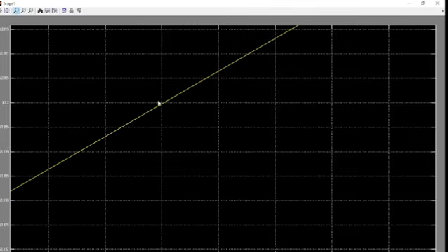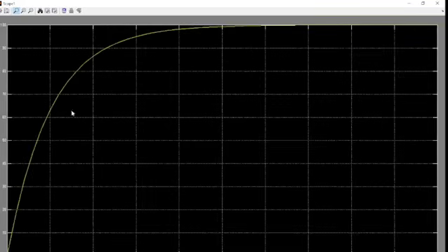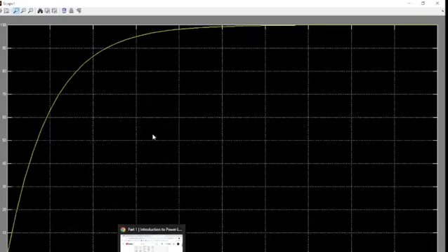So you can zoom into the particular area. At t equal to 1, the voltage is about 63.2. So you can note down such readings. Again, go back to using autoscale, and you can zoom in for some different values and note down the readings. Once the readings are noted down, then you can draw the graphs or do the remaining calculations.